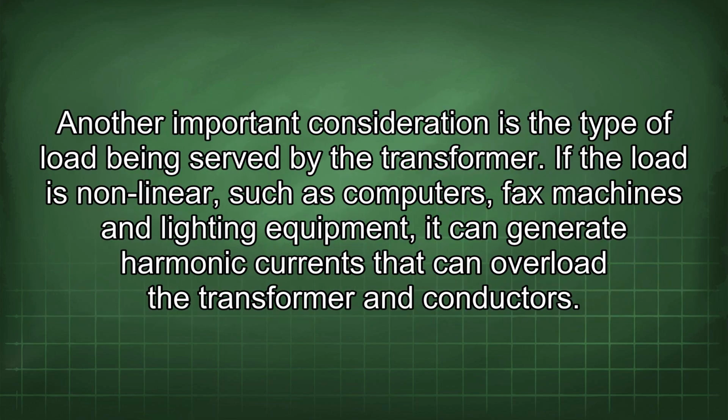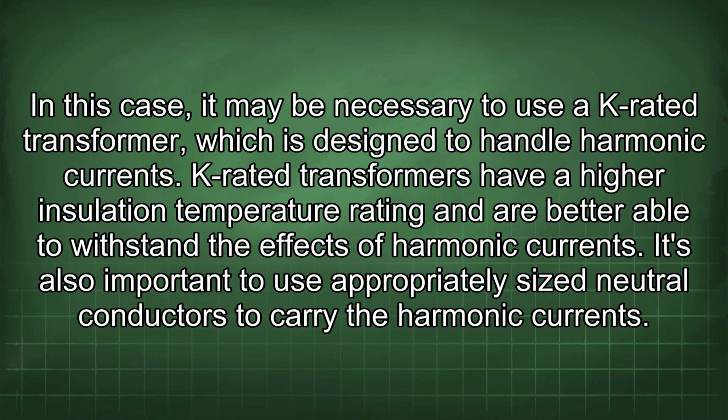Another important consideration is the type of load being served by the transformer. If the load is nonlinear, such as computers, fax machines, and lighting equipment, it can generate harmonic currents that can overload the transformer and conductors. In this case, it may be necessary to use a K-rated transformer, which is designed to handle harmonic currents. K-rated transformers have a higher insulation temperature rating and are better able to withstand the effects of harmonic currents.